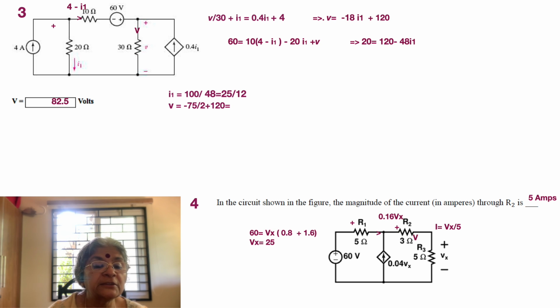But now moving to the other side, we also see that we have a current flowing through the 30 ohm resistor, which creates a voltage by multiplying that current by 30. So we can now write out the current that is flowing into the 30 ohm resistor in terms of what we are supposed to find out, which is V, so it is V by 30.